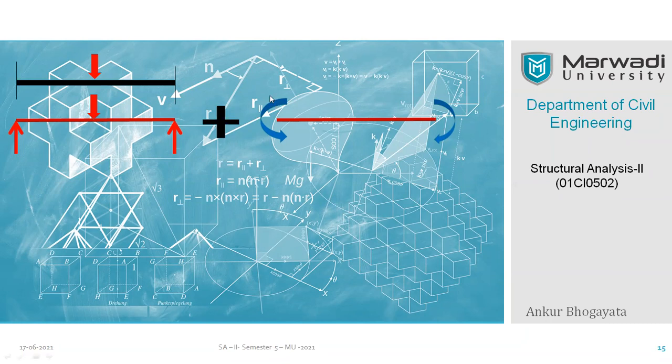Just now, for the sake of understanding, when you want to offer the fixed end moments, it is just a rectangle, that's all, right? So now I have separated both the structures. Now let's see what's next. See, now here the complete moment is a sagging moment, so my bending moment diagram will be positive, right? So I'll be drawing it below the line, as you know, right? For the sagging moment, the bending moment diagram is developed below the line.